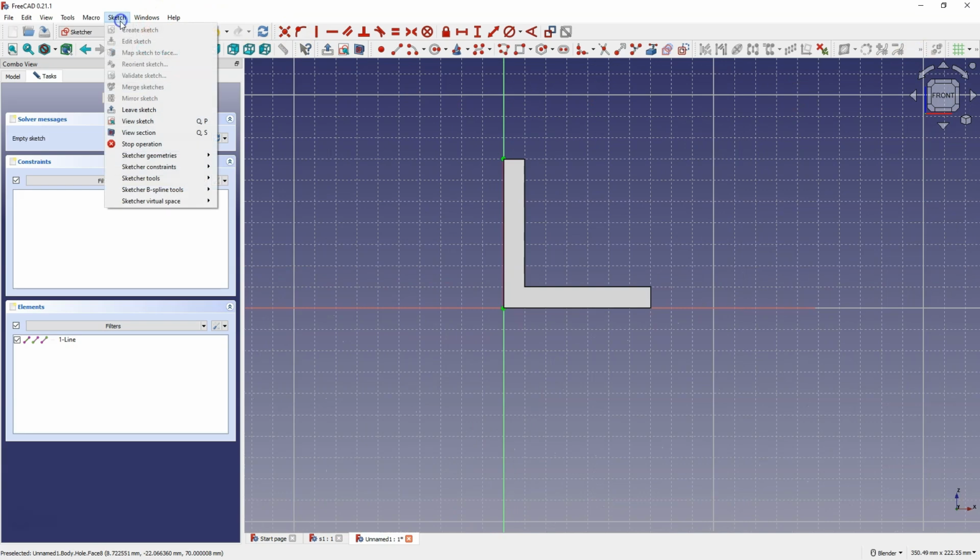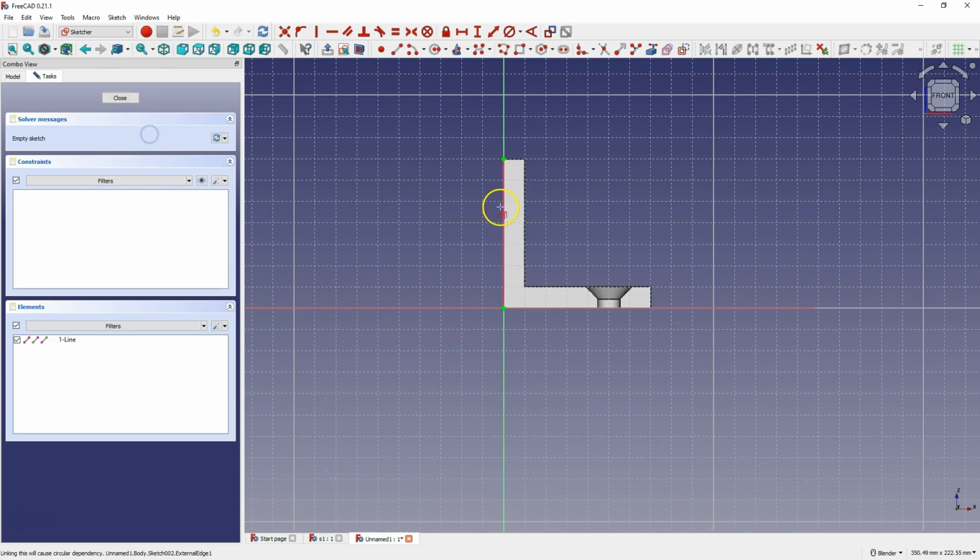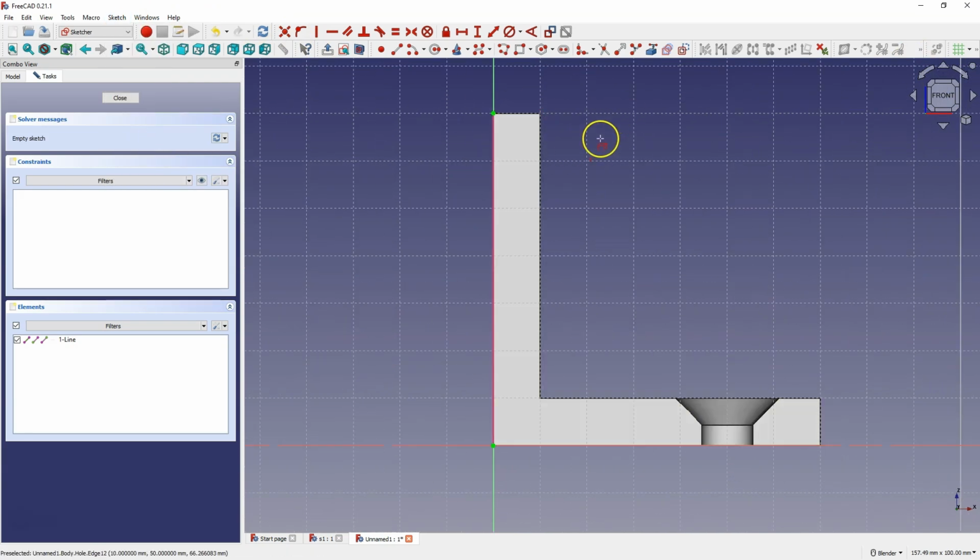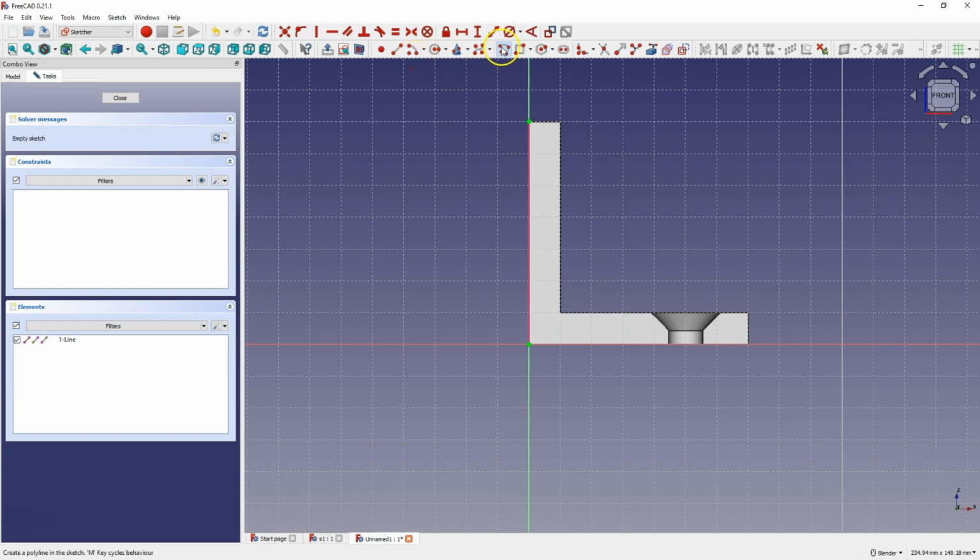But if we turn on the section view, it will already be clearly visible. And now select Draw a Polyline and hover over this line so that the beginning of the newly drawn line is connected to the reference line on the model, and draw the initial shape. Here, as in this case, we will constrain the next point of this line to this line.